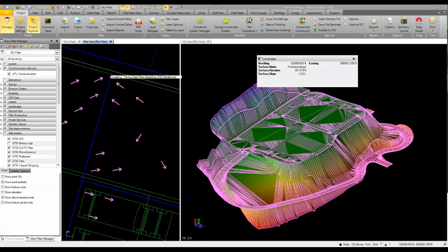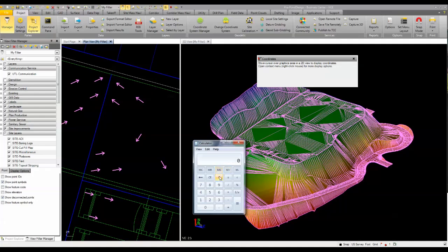We're going to drop it down a minimum of 4 feet. So if we open up our calculator, we can do, let's see, 452, right? Is that what we determined? So 452, we're going to minus 4 feet. 448 is going to be our starting invert. We know we've got 850 feet. We're going to multiply that by 0.5%, so 0.005. So we've got to drop it another 4.25 feet.